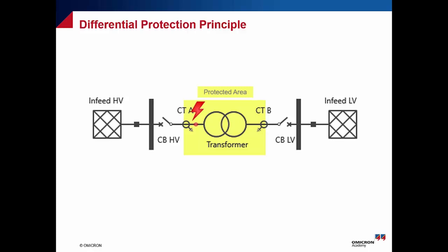The same thing also if we have an internal fault between the two CTs, not only inside the power transformer tank or inside the winding itself, it should also issue a trip. As you see here, it's a kind of a fault between the CT and the winding. It can be maybe between the bushing and the winding, and should also be considered as an internal trip because the differential will recognize the fault between the two CTs, between the two sides as you see it right now.